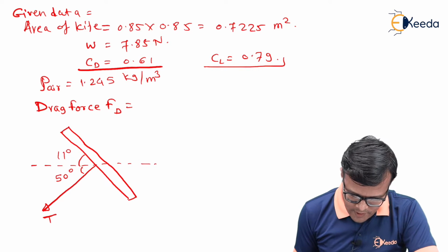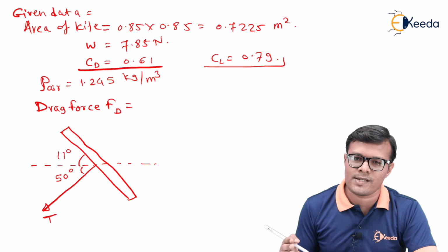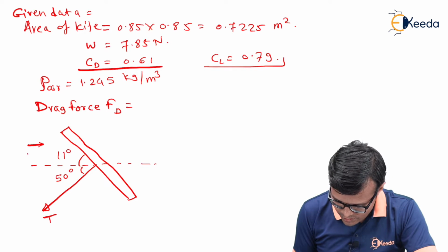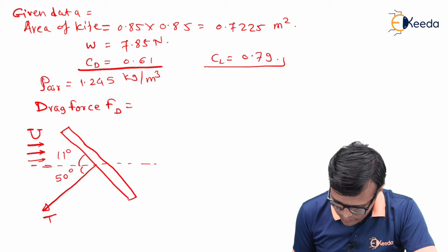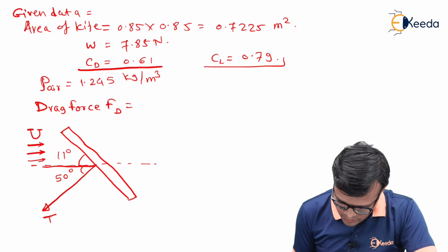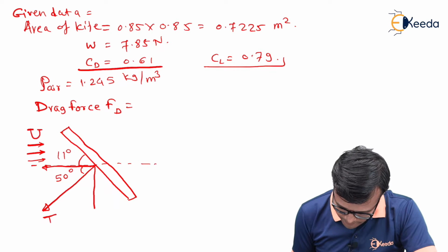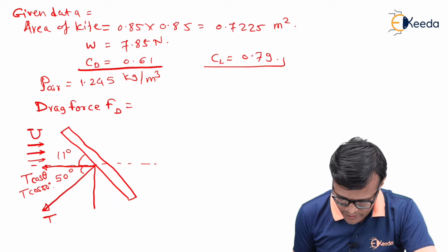If I want to resolve some forces, drag force is that force which is in the direction of velocity. So if this is the direction of velocity, that is u, then we have to calculate a component which is resolved in this direction. So that will be T cos theta, T cos of 50 degree.